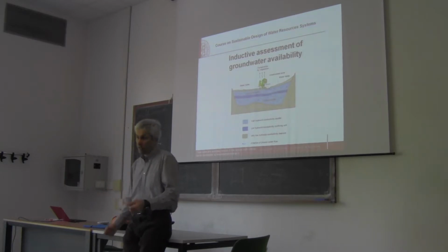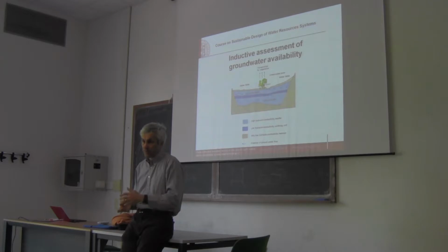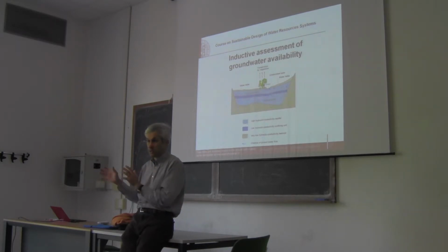Let's suppose that you make a stress test on a groundwater resource, and you see that even after taking a limited volume of water, there is a rapid decrease of the groundwater level. So your conclusion may be that the recharge is very limited. But actually, it may also be that the recharge is very slow, meaning that the reaction time of the aquifer is longer, and some aquifers are recharged only in some seasons.